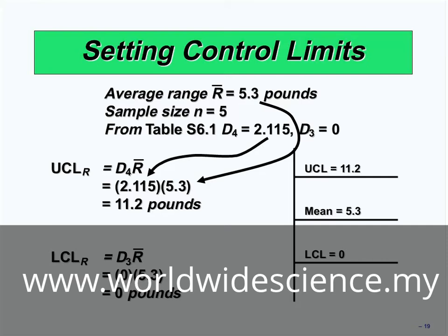In hour 2, the R2, for example, is 8. In hour 3, the range, or R3, is 5 or 6, for example. These numbers should be plotted in this chart. All of the spots should be located between LCL and UCL. If one of the spots is out of this area, the process is not under control. That was our chart.